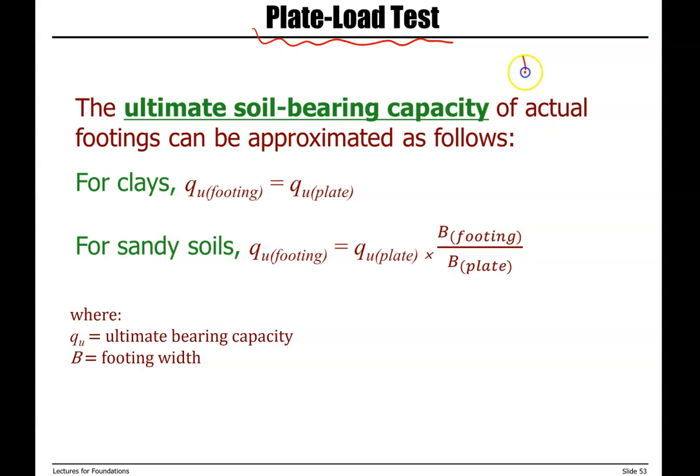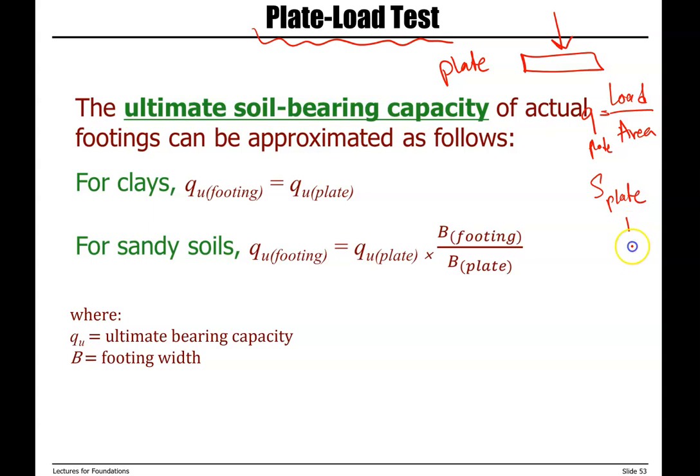So we use a plate, apply load, we measure load per unit area or capacity of plate, and we measure settlement of plate. Then we use these formulas to calculate bearing capacity of footing and settlement in footing.